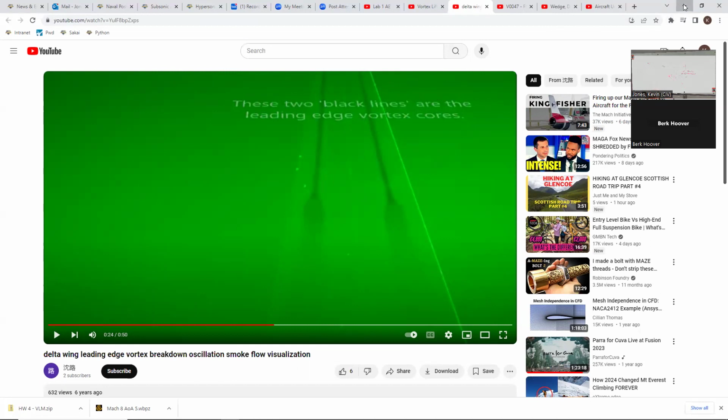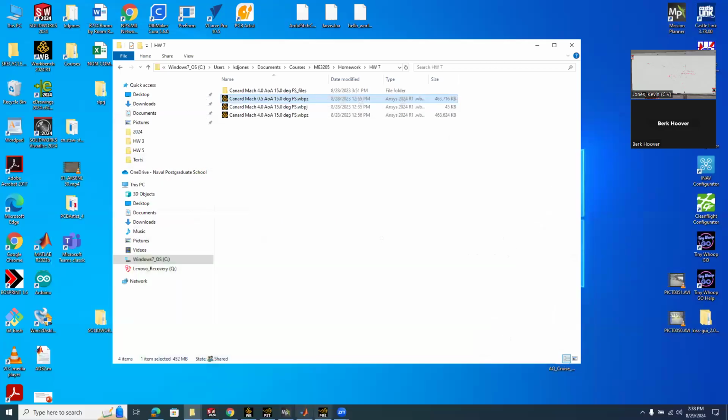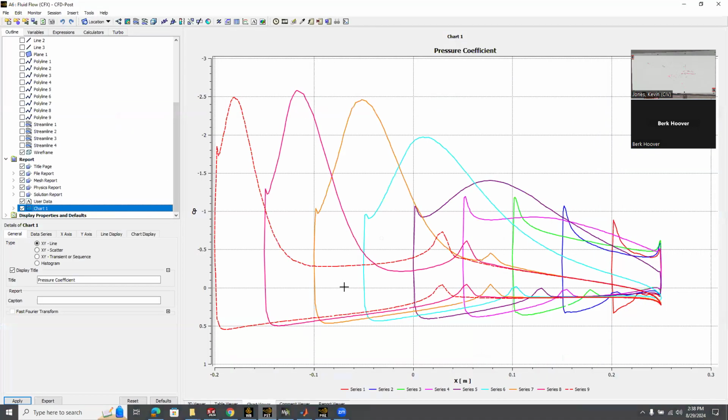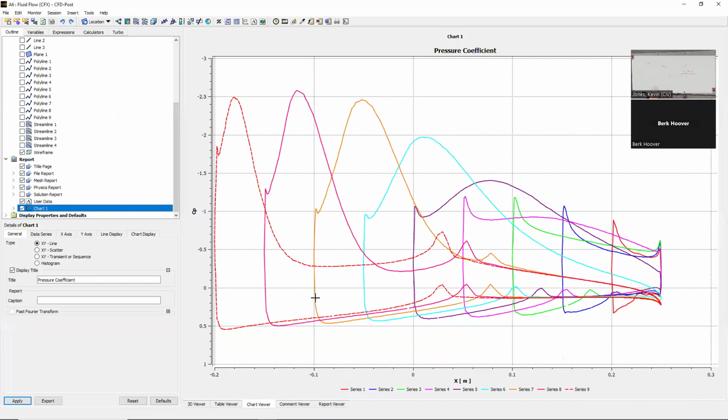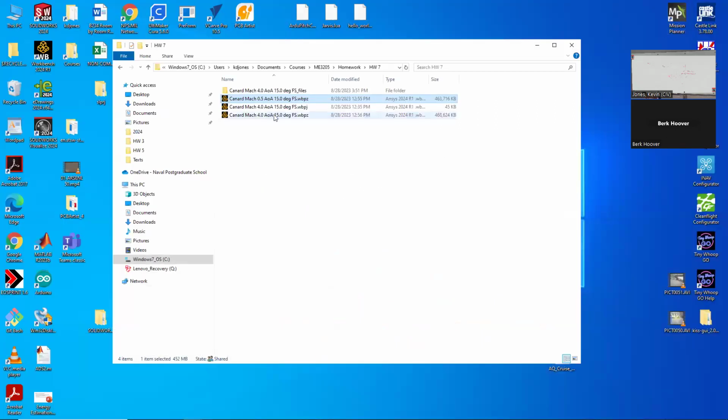From the missile perspective, the place where we win is that this super sharp diamond airfoil that we use for this problem, which would normally be useless as a 2D wing in subsonic flow, is suddenly really good in subsonic flow if it's swept, and then also works great in supersonic flow. I think I actually have a supersonic solution on it too.